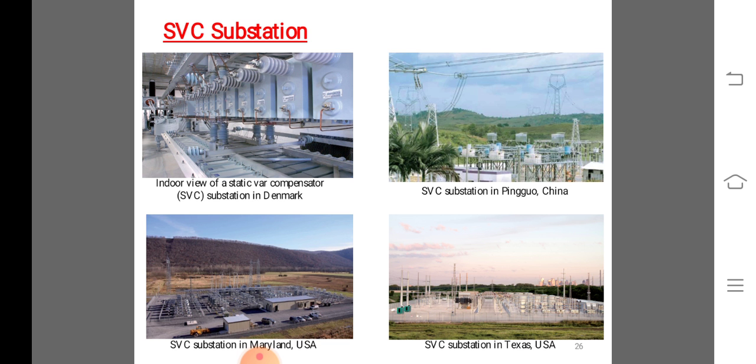Some of the following requirements are to be borne in mind while designing a compensator. First one is reaction should be possible, fast or slow, whenever demanded. No switching of capacitor should take place at that time, to avoid additional transients in the system.